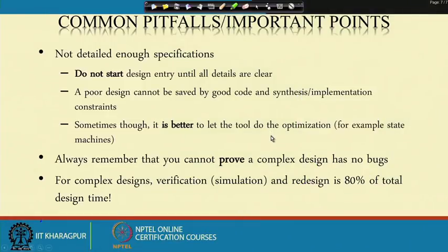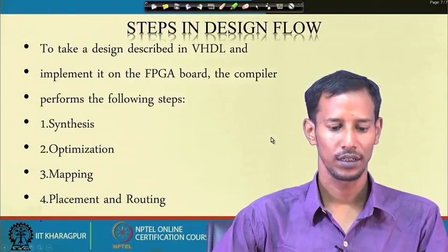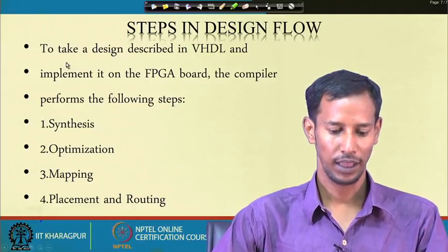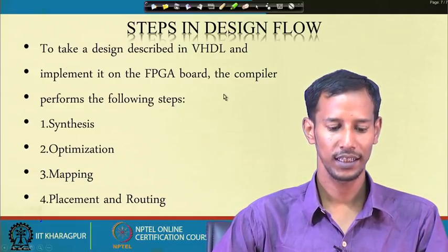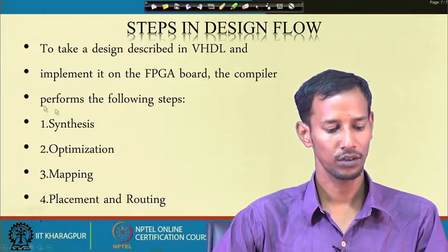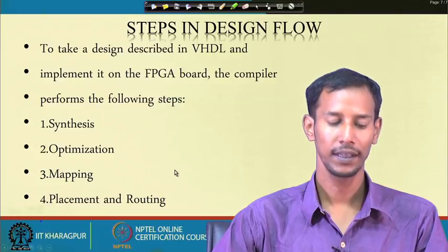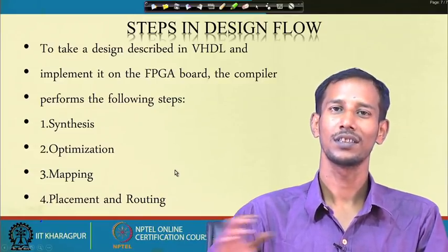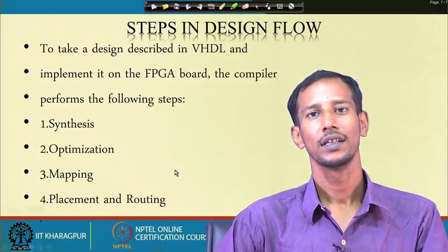So, the steps in this design flow are: you have to describe using HDL, then choose the implementation platform, then synthesis, optimization, mapping, placement and routing. These are the steps involved in the design flow.